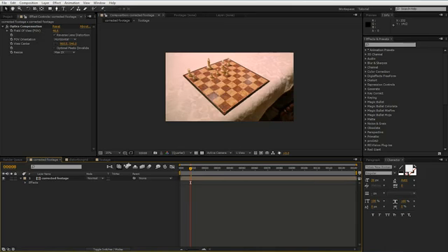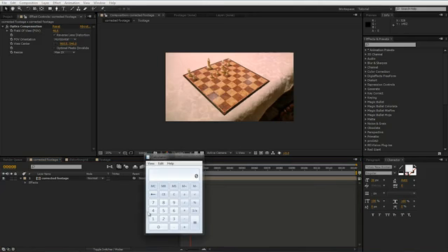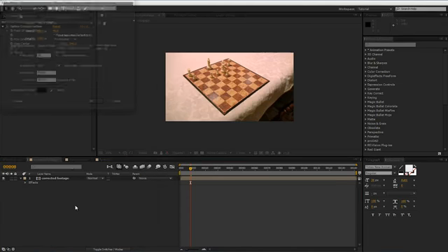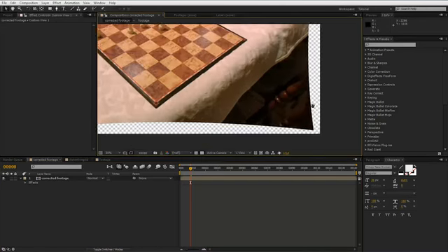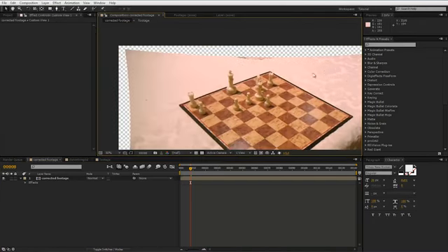So for this example, where we don't have too much barrel distortion, I say we might need to render it out 20% larger. So let's go 1920 times 1.2, and we get a value of 2304. So I'm going to type in 2304, and if you have the lock aspect ratio, it gives you the height for free. And we can see here that, yep, we've got all our bases covered. We might have a little bit more than we need.